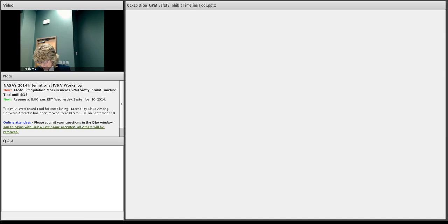So to make sure everybody understands, these top three inhibits are the electrical inhibits controlled by software. So when the three are green, they're in place. When they're red, the software has sent a command to the inhibits to have them close.